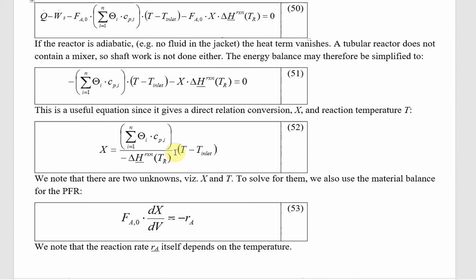And then, of course, now we want to couple it to our mass balance. So this is our design equation for the plug flow reactor. And remember that this r_A was where the temperature dependence arose. So the term on the left-hand side just tells us how the conversion changes across that reactor, the number of moles as it varies along the volume of the tube. Whereas the right-hand side tells us what nature is doing. So nature is giving us a particular reaction rate given a particular concentration and a particular temperature. So that's where the temperature dependence will arise.